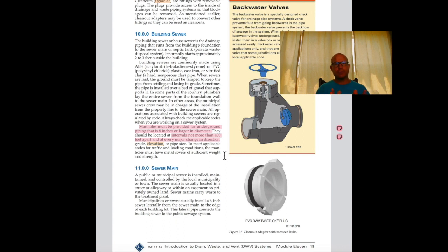So all of them probably need some form of clean out, but there's one that is very specific in needing 2 clean outs. So just know what it's asking and know how to look for those in words. Okay, so you have a building and you have a combination. City sewer, clean out at the building, you're going to have two kinds of clean outs there. I don't care how far apart you are from it, the building's got to have a clean out. You've got a combination of the street, you're going to have a manhole which can be used as a clean out.